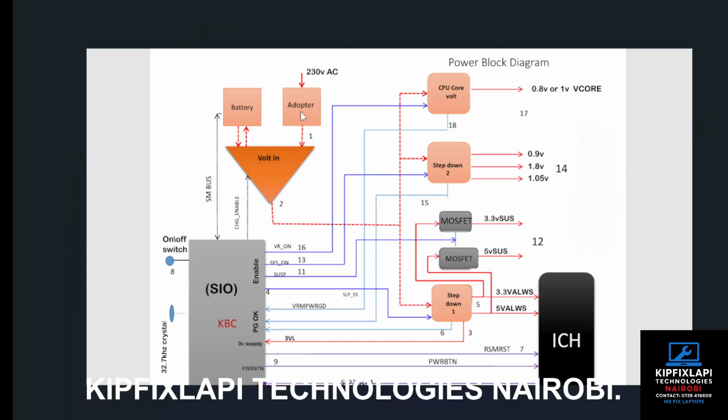From here, we shall be having the power port. First, we start with the power adapter, which supplies the voltage from the wall socket. It supplies in the form of AC, which inside the adapter is converted to DC voltage, because the motherboard of any electronic device needs direct current to power on. Then it supplies the voltage through the power port or the DC jack,